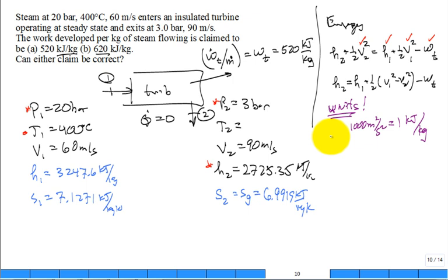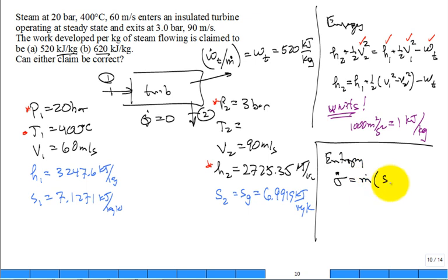We go to the entropy balance, and we want to check. We want to see what sigma dot is for this problem. What we find is that sigma dot is equal to the mass flow rate times the entropy exit minus the entropy inlet. A little bit of algebra right there, but you get that for the second law. We stick in our numbers, but you hardly even have to stick it in. Here, just do this. Divide this by m dot, and now it's equal to.